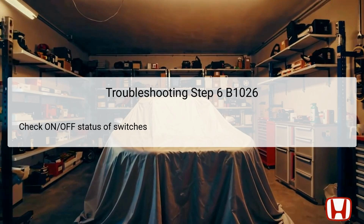If both indicators are off, it implies that the problem may reside within the switch itself. Conversely, if either indicator is on, there's a clear indication that the switch is operational, and further troubleshooting is needed. This step aids in diagnosing whether the switch outputs are functioning correctly, and whether they are consistent with the expected behavior. Monitoring the live data precisely is a practical method for isolating the issue within the circuit.